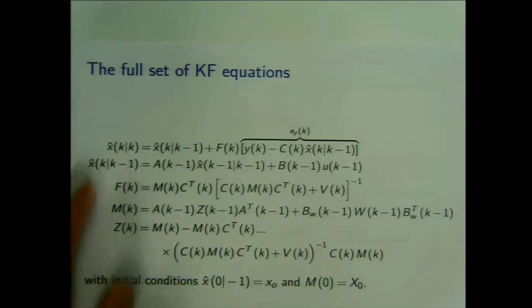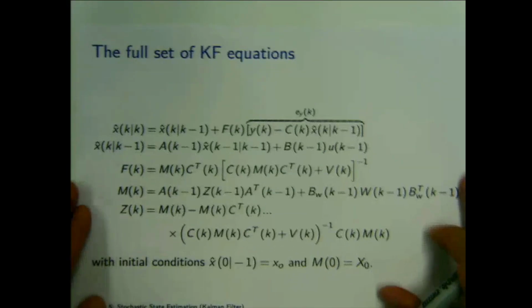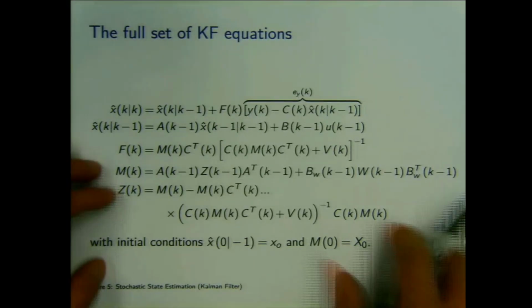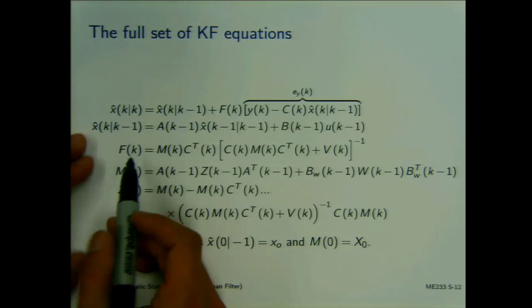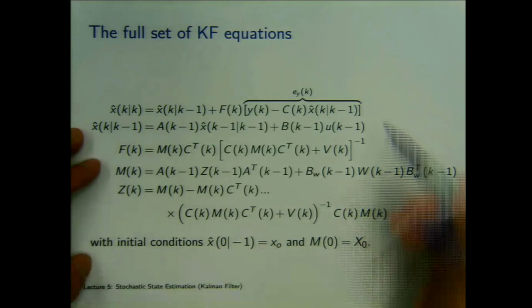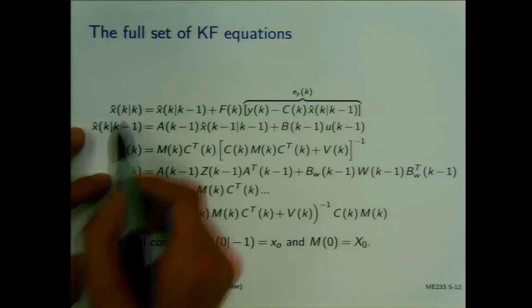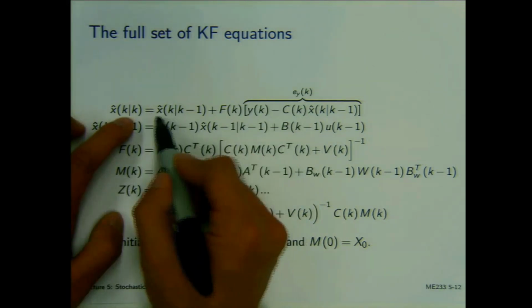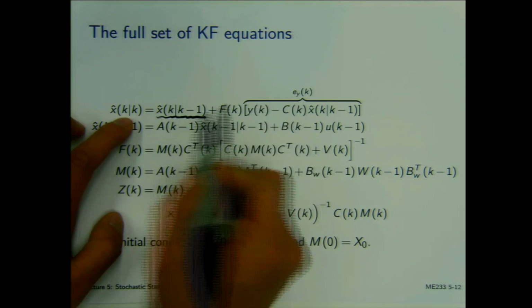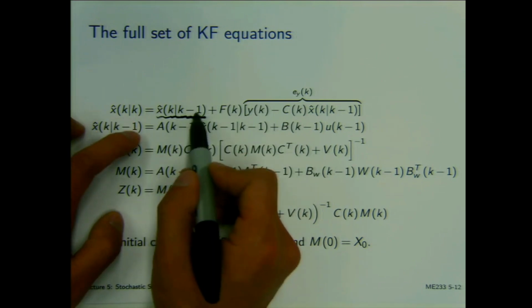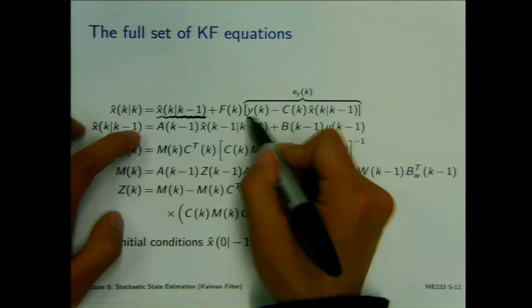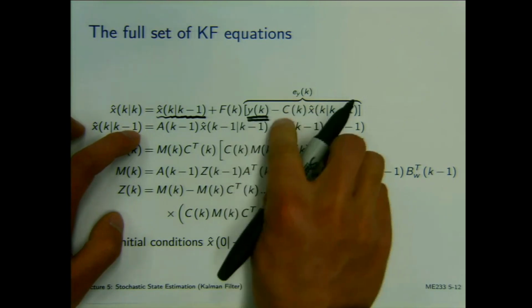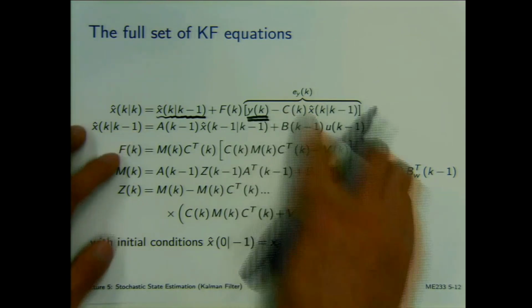As you see, it's just repeatedly using the properties of least squares. These are the central equations for the Kalman filter update. Let's take a moment to read these. So the estimation of x, given all the information up to k, is improving the estimation given all the information of k minus 1 with the new measurement yk. Okay? This is how the first equation looks.